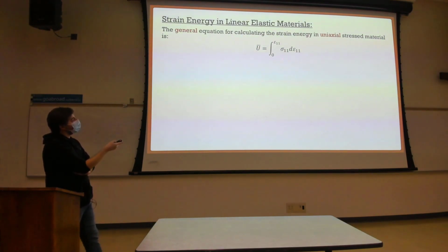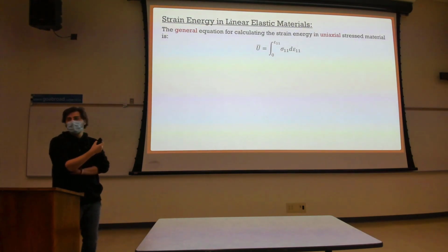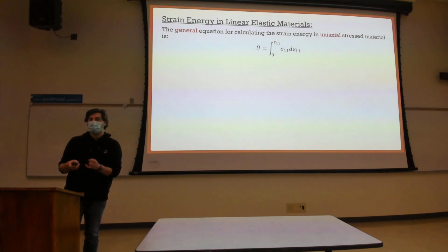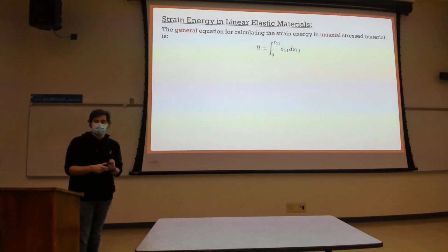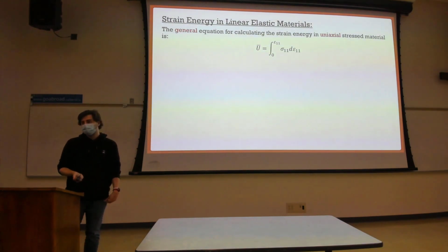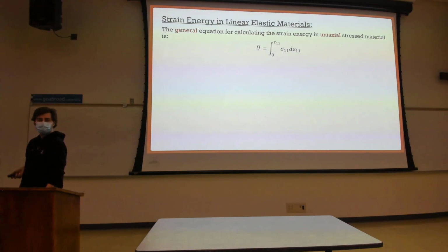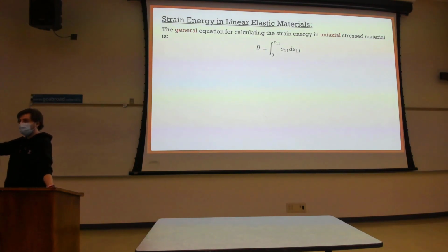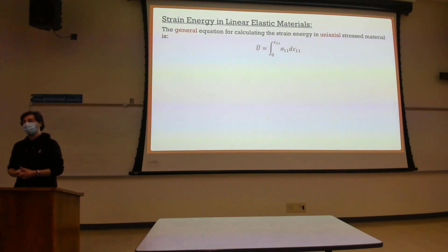Because if you look at the question, I give you what the stress formula is in terms of epsilon, and all you have to do is integrate from 0 to whatever strain you want. So in the assignment, I say I want the peak strain, and then I want the crushing strain. So all you would do is just change the limits of the integral. But who likes doing integrals? Put up your hand. Who's a big fan? Like Clayton, yeah, I'm very excited to do this. No one. That's why when we have linear elastic materials, things become nice.